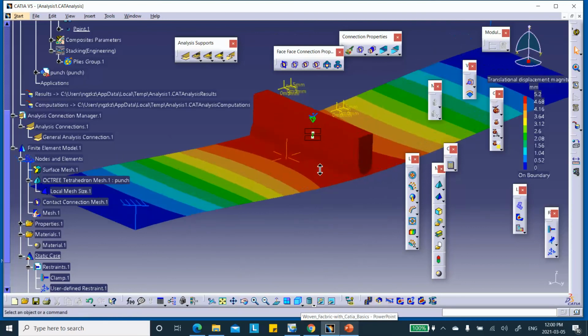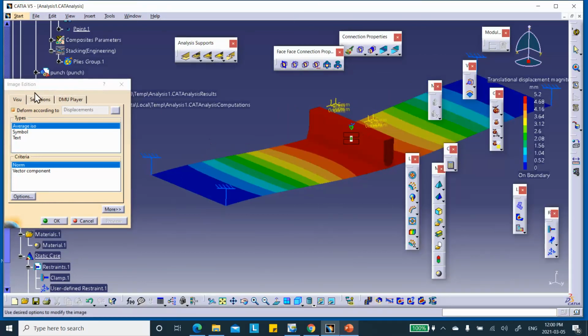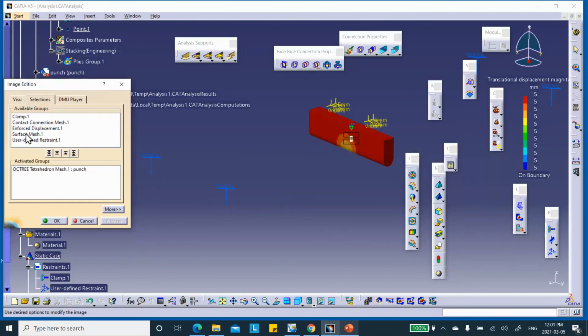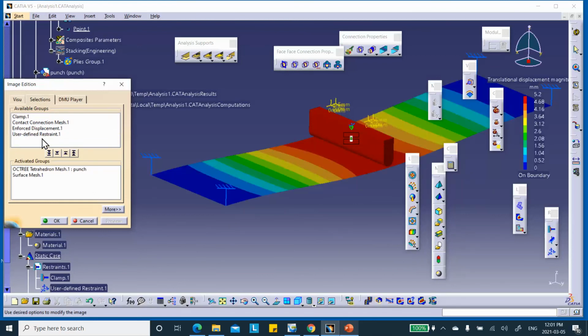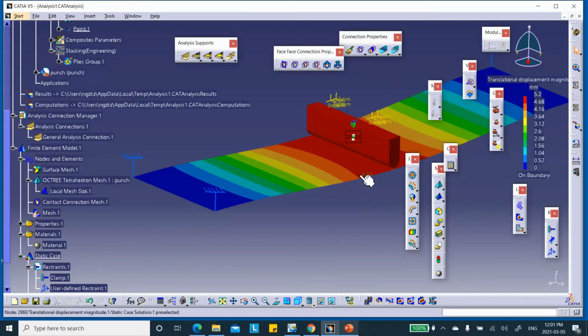Except that it also shows me all this garbage here, which is the contact elements and things like that. So I double clicked on the plot on the screen, and on the selection, just show me the 3D solid element and the surface. Don't show me all those intermediate shell elements. Now, incidentally, if you want to see the elements, you go there, click on this question mark.